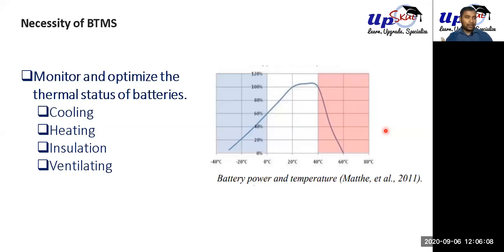The more temperature you give to the battery, it will increase the resistance. The increased internal resistance will create more heat. So the cycle goes on. It's a snowball effect. This situation is called thermal runaway. When thermal runaway is achieved and you don't stop using the battery, this battery will surely catch fire or explode, because it will reach temperatures upwards of 250 degrees centigrade. If the battery is very strong and not exploding, then it might even reach a temperature of 400 degrees centigrade.